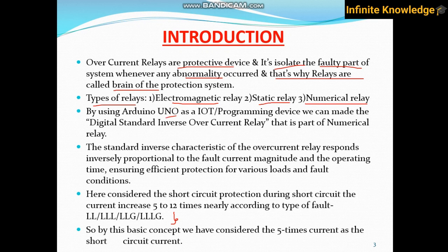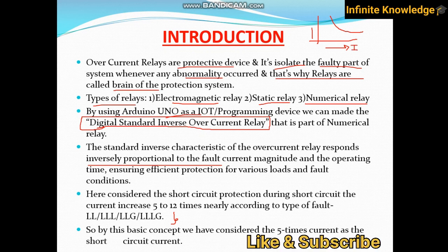So by using the Arduino UNO as a programmable device, we can make the digital standard inverse overcurrent relay. Why are we using the standard inverse? Because all the relays are following standard inverse overcurrent curves, which we will cover in the next slides. The standard inverse curves of the overcurrent relay respond inversely proportional to fault current. It means as your fault current is more, your time to trip is less.